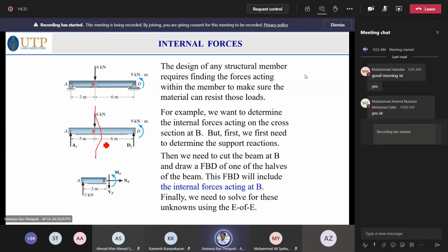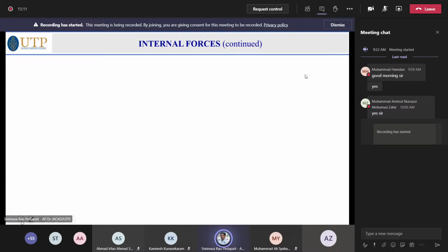That section will have one reaction, the one which is here, and then the shear acting at the point B, and because you are cutting here there is a normal reaction at B. This is how the free body looks when you cut a section along B. This method of sections we already practiced in the case of trusses, so we are doing it here also. The concept of section is not new for us.